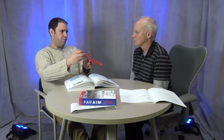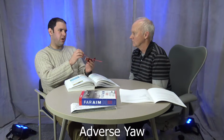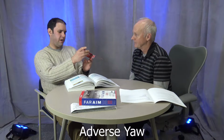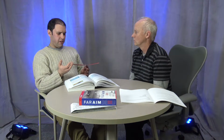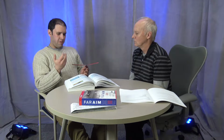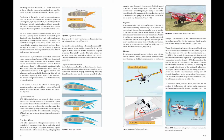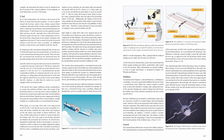Correct. There are various different ways that ailerons can be built in order to minimize that tendency to pull towards the outside of the turn, which is called adverse yaw. When the aileron pulls the nose towards the outside of the turn, you have to use rudder to keep it going straight. There are various designs of ailerons that have been come up with in order to reduce that and make it so you don't have to use as much rudder in turns. And they go into detail on that, pages 6-4 and 6-5 here of the Pilot's Handbook of Aeronautical Knowledge. Talk about the elevator here on 6-6, 6-7.